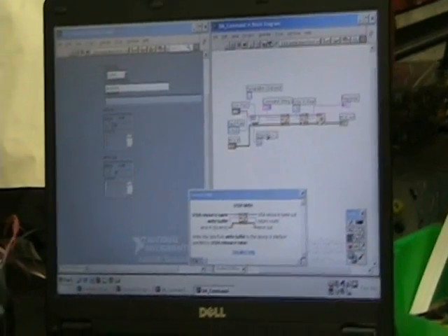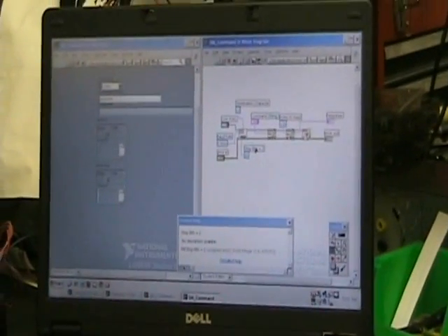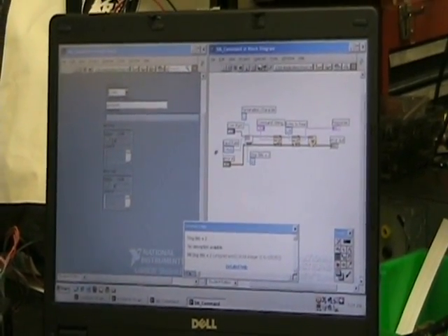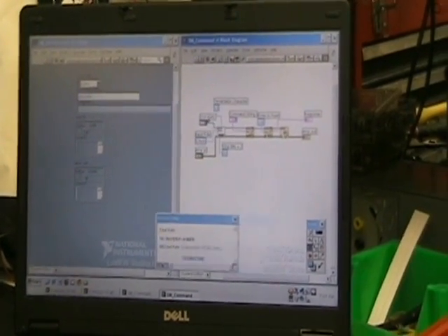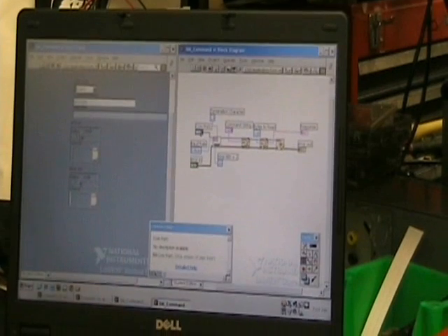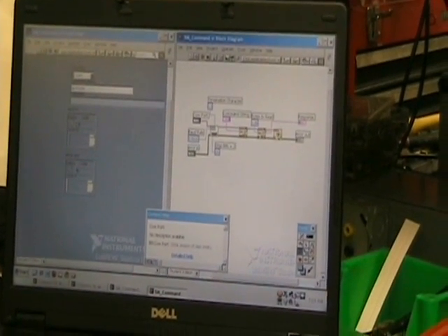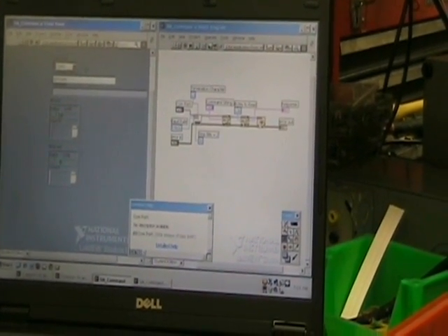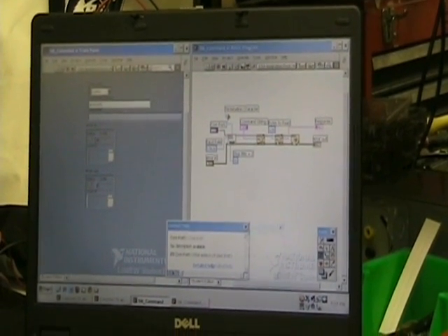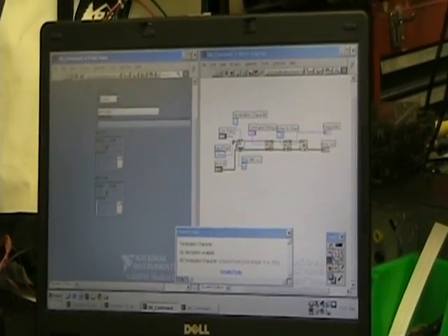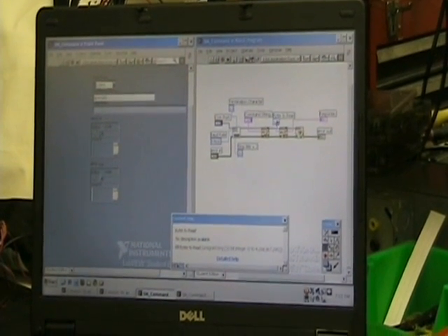And as you can see, we're set up to talk with 2 stop bits with a baud rate of 57,600, and then to ask what COM port. So that is run out as a question over here on the front panel, the COM port. And the termination character is 13 and 128 bytes to read.